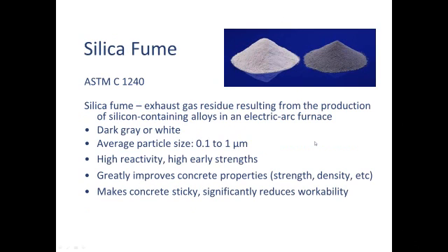Prior to metakaolin coming on the market, the only really high-performance pozzolan that was available, and not very readily available, was silica fume. Historically, the only silica fume that was available was the normal stuff that's sort of a dark bluish gray. There's a photo up top of a white silica fume and a gray silica fume. And the white silica fume is much more expensive, but equally as effective.